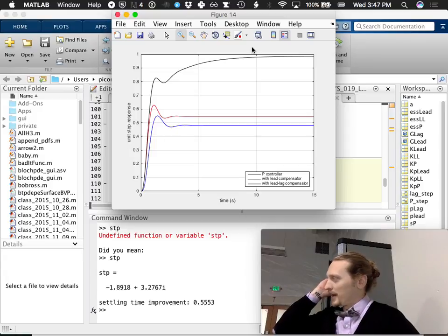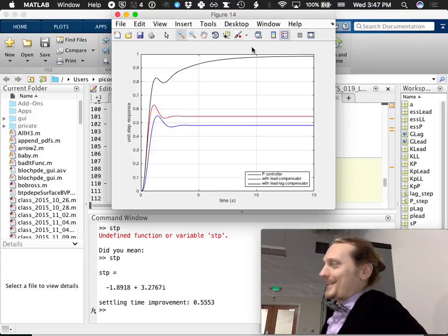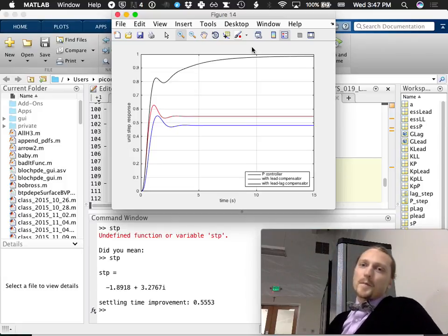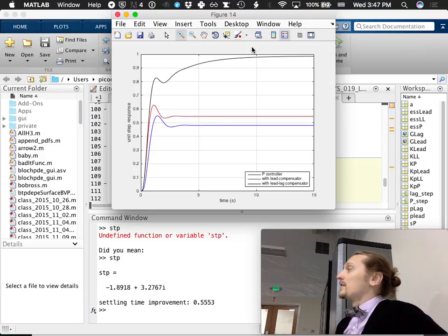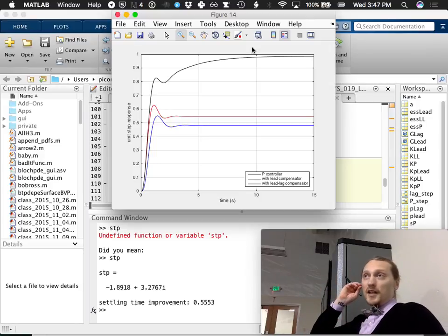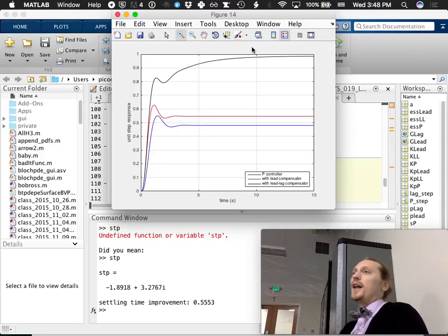I've never seen anybody actually try to precisely define that transient response. So how in the end can you justify that what we've done, all the way down to the end, would be the top curve? Yeah, right? It's definitely the best option we've got so far. Can we just keep adding zeros or something to try and increase that settling? Potentially, yeah. If you want to work within the framework of just lag leads, you couldn't do that. But if you wanted to go outside of that, you could add zeros if you wanted to.